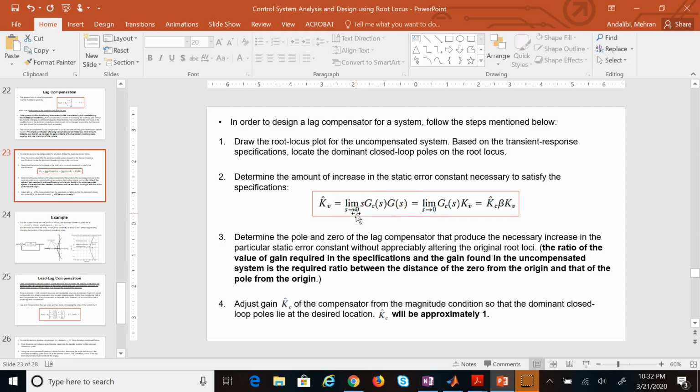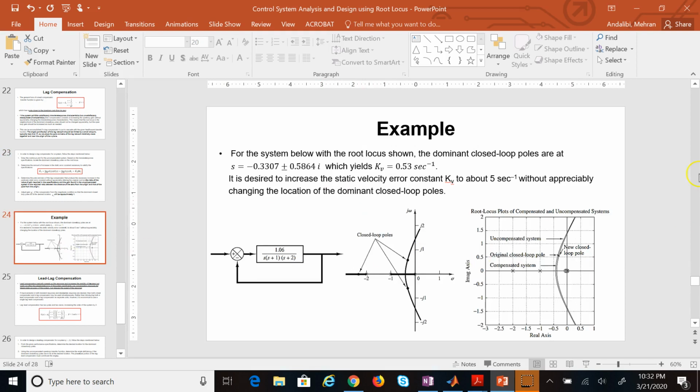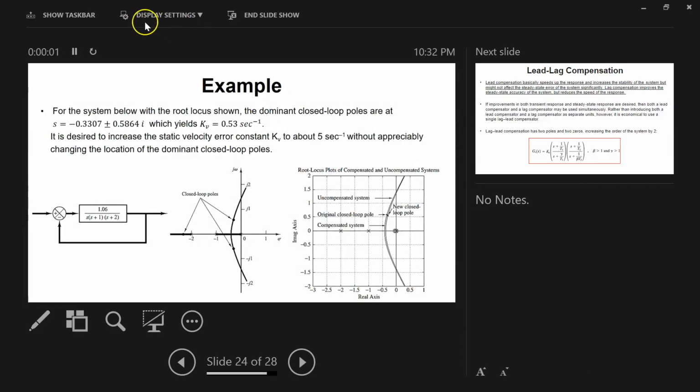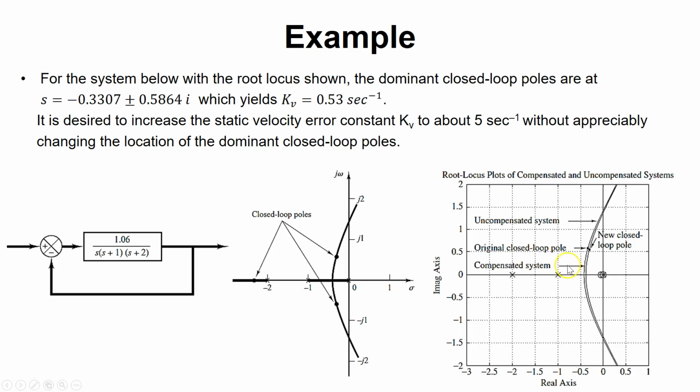Okay? So your location in the complex plane determines the steady state error; the steady state behavior of a system is only determined by how the system appears around what? Around 0. So the steady state response does not care how the root locus looks where it's not close to the origin.